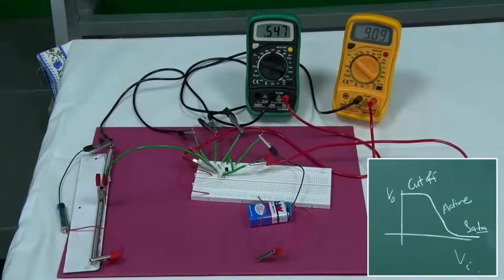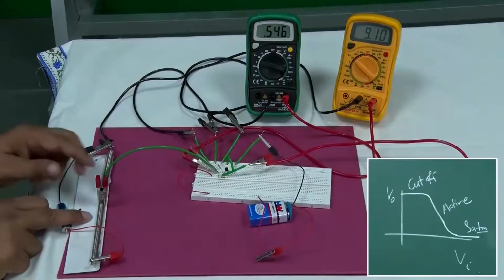The transistor is now conducting, the collector is doing some job, there are carrier injections from the emitter to the base, there is some IC, and there is some RL into IC drop on that 10 kilo ohm resistance, and therefore, the output voltage of the collector has gone little bit down.